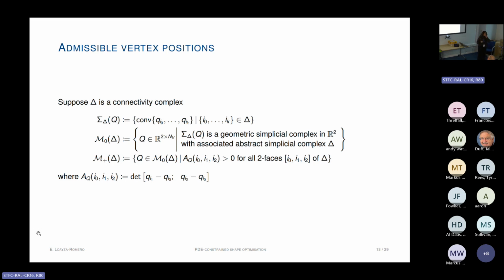So we thought, okay, let's use conformal meshes, right? We're not going to have hanging nodes. The intersection of the different edges or faces is going to be either the empty set, an edge, or a point. And it turns out that exactly this definition of conformal meshes can be expressed in terms of simplicial complexes. In fact, this is a geometric simplicial complex. So in order to define our triangular meshes set, we use this language of simplicial complexes.